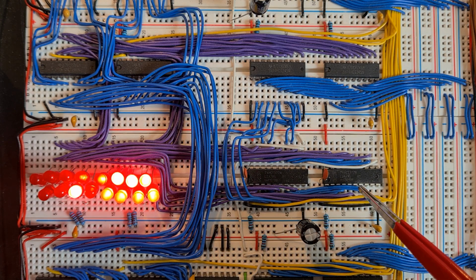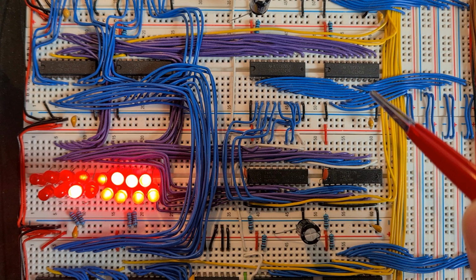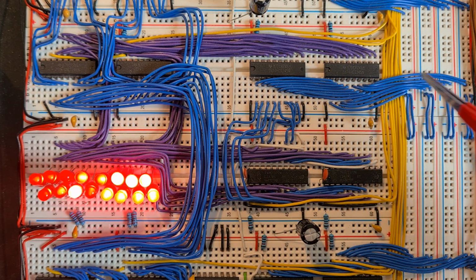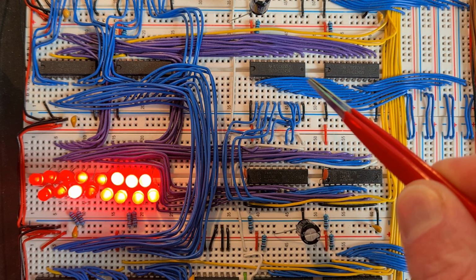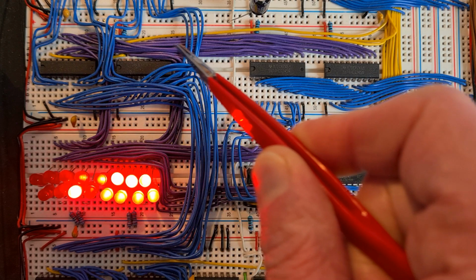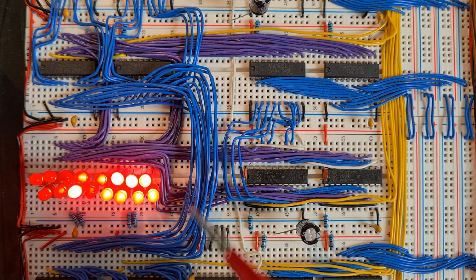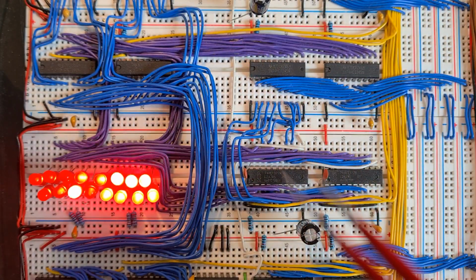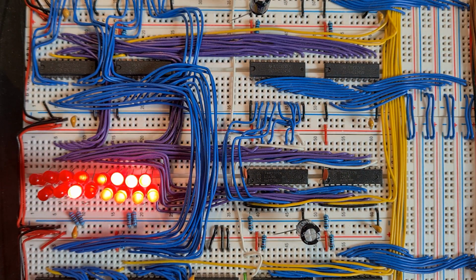So these are the two register chips that hold the 16-bit value of the new address register, and these are the bus transceivers to connect the new address with the data bus. This is the part where the new address register is connected to the address bus, which is going down to the stack pointer and going up to the program counter, and again the flickering, in this case red LEDs, are the current value of the new address register.